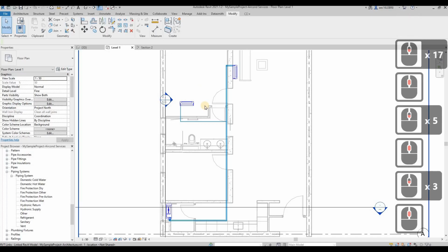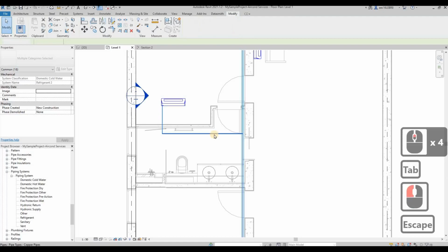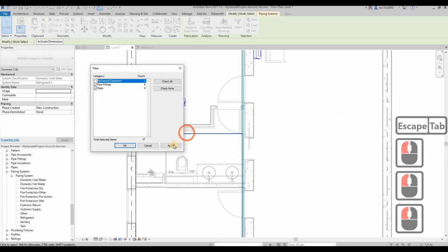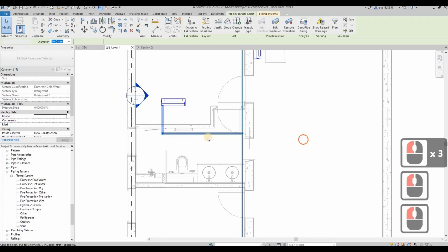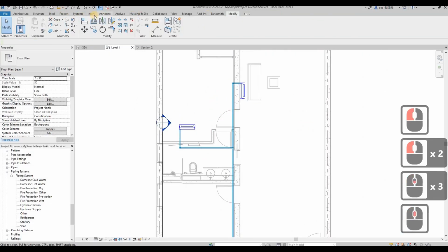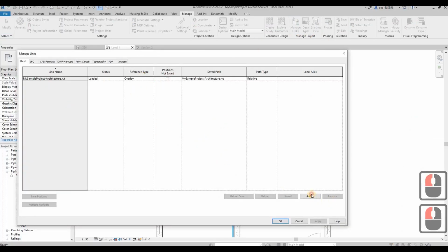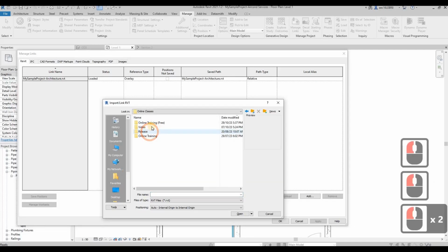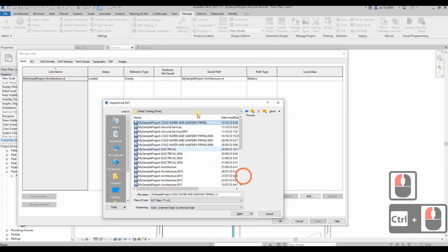Then you load inside. Okay, before that, add in your installation. Okay, select all the pipes here by pressing tab key. Then use the view filter here to filter away the mechanical equipment. Then you can add in your installation. Okay, that's how easy. So you need to link in your cold-water and sanitary piping models. Okay, go to here online, then your online training, cold-water and sanitary piping, and also load in your electrical.